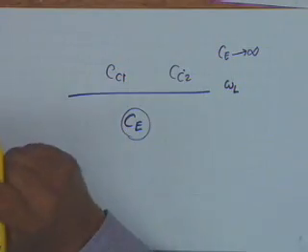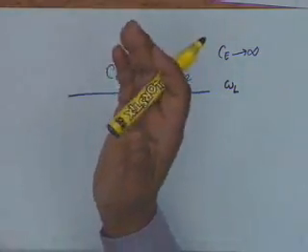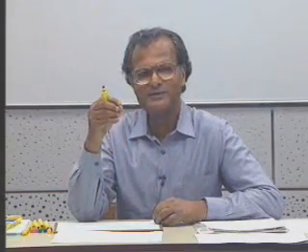Now one can be fussy and one can say, why don't I optimize? Why don't I optimize by using the minimum possible capacitances? That is, I use all the 3 together and then try to find out by solving a 6th order algebraic equation numerically what omega L shall be. It's not worth it, because large electrolytic capacitors are available, plenty. If space is a premium, if space is a problem, you might have to do that.